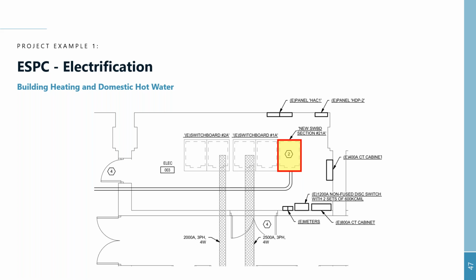As Teresa mentioned, electrification requires a big chunk of energy and power at the same time. It's not as easy as it sounds, and requires a lot of coordination, field coordination at the beginning of the project. You have to do a deep dive and find maximum demands, electrical bills, and information on the equipment. You have to go in the field and maybe hire an electrician to open equipment and look at the configuration, to make sure that if you need to connect and expand the existing equipment, you have the space and the capacity to do it.